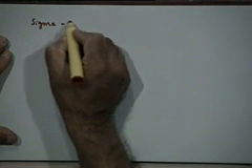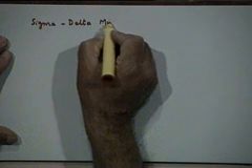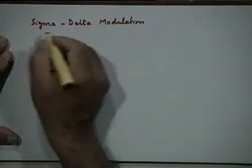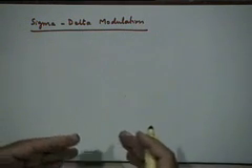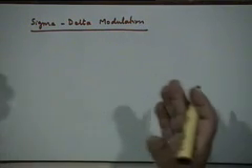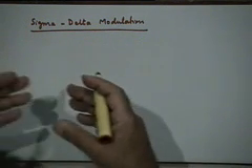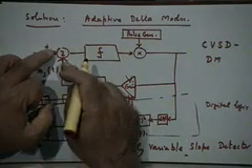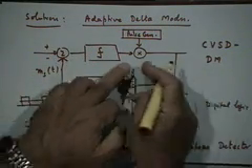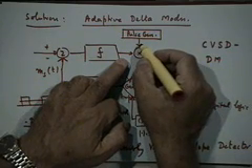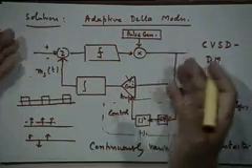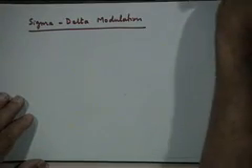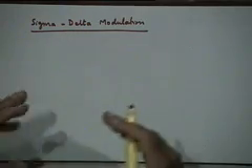One last concept in the context of delta modulation is a very important variation of delta modulation, which is called sigma delta modulation. These are very interesting terms, delta and sigma. As you can see, the circuitry is extremely simple, and all you need is a comparator, a limiter. Look at the circuit diagram. What kind of components do you need? Adder, subtractor, a limiter, extremely simple to make. A multiplier in which one of the inputs is a pulse, extremely simple to make. So that is why the delta modulator was a very popular method at one time, and it has again become very popular these days.